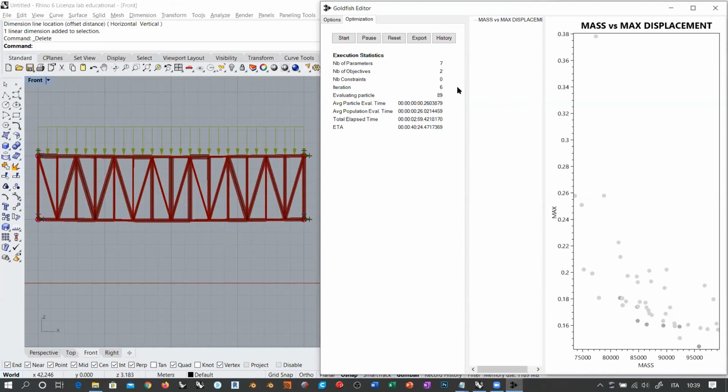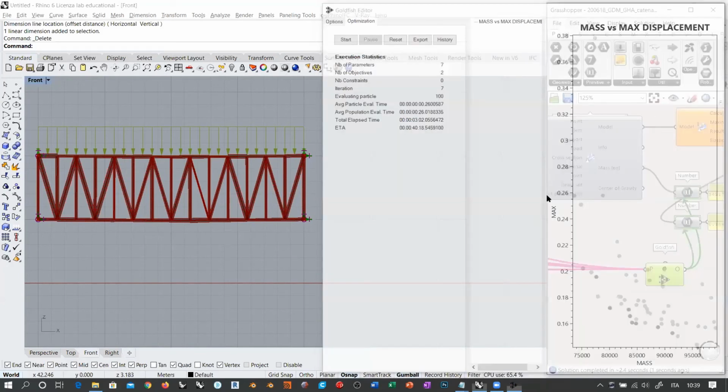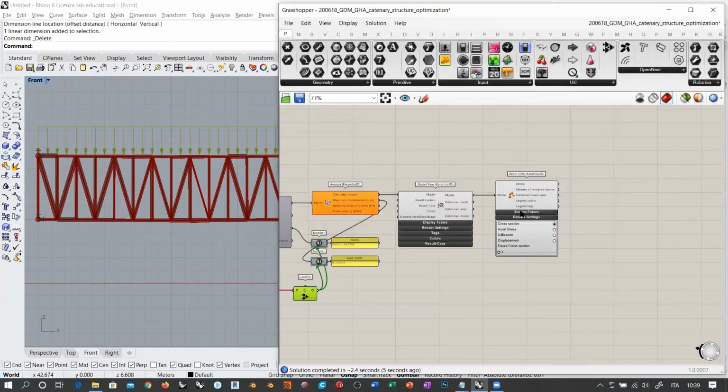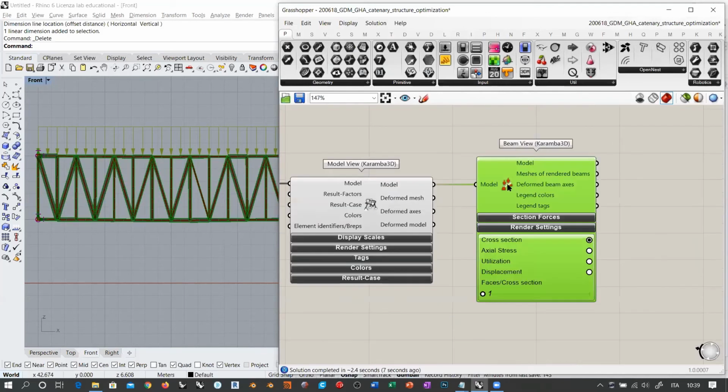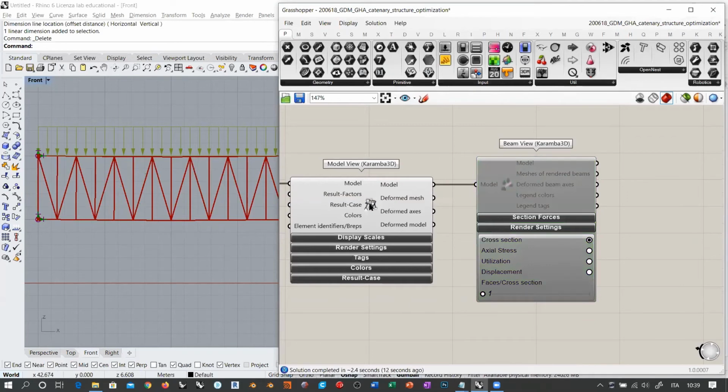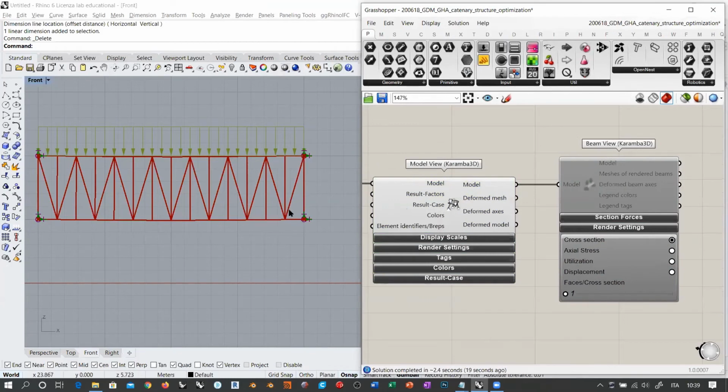But one thing that you can do eventually, let me pause this. Okay, let me close it. And also let me do something like this. I want to deactivate this, so Control E, and leave only the model view active. So we have no rendered mesh right now. Remember that this is also part of the time-consuming processes. Rendering a mesh is always occupying the processor, the CPU, or the GPU in this case.